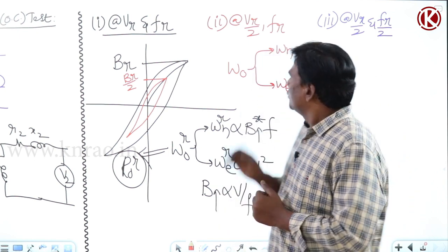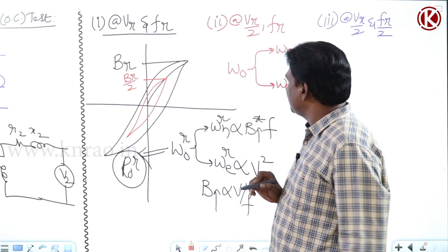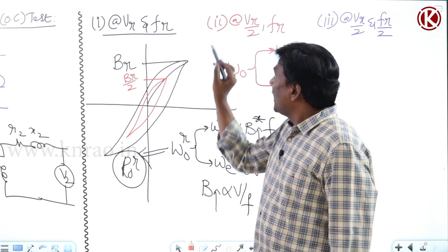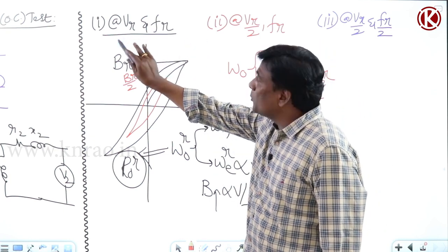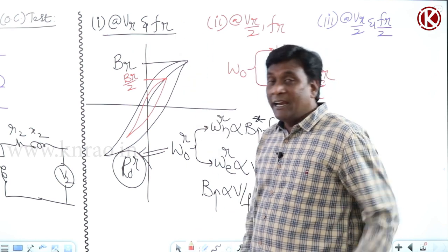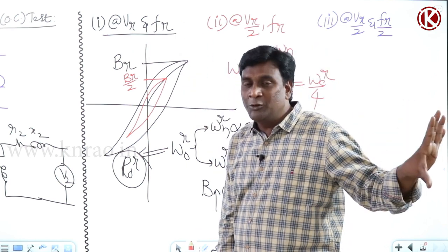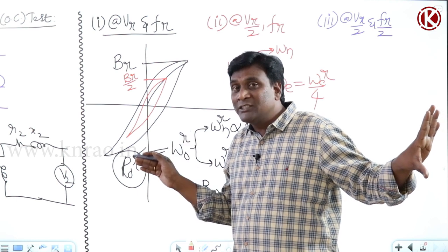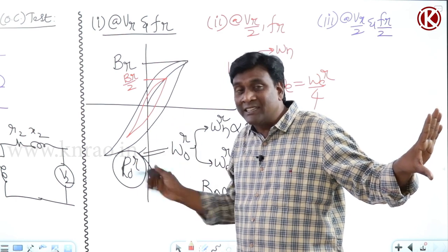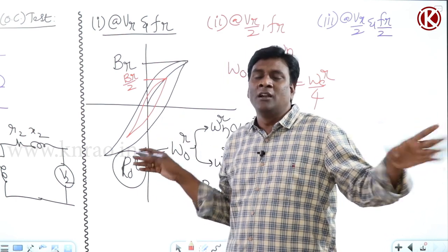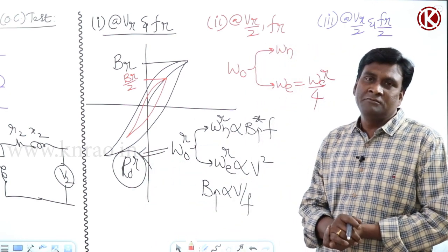Getting my point, right? Ultimately, my transformer is supposed to be used at rated voltage, rated frequency. In my testing conditions also, you are supposed to get the same value as in practical utilization. Otherwise your test is going to go in vain.